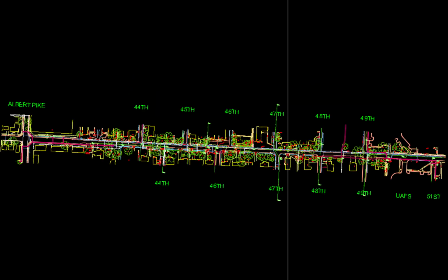Using this procedure creates an existing topo drawing having minimum layers and minimum size that is XREFed into the various construction drawings. Any changes made to the topo drawing will automatically be updated in the construction drawings.